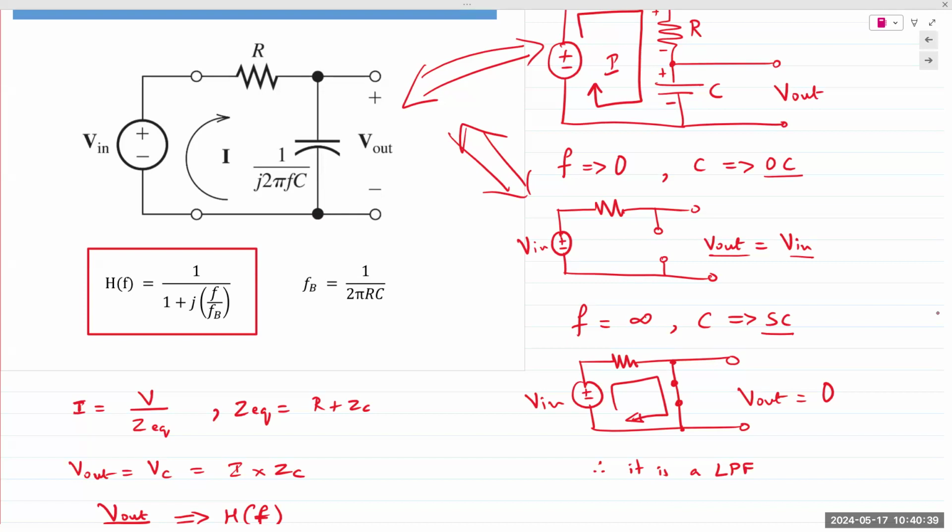So all four circuit diagrams are exactly the same circuit. There is no difference. It's only the behavior of the circuit that changes because capacitor impedance changes with respect to frequency. We are simply modeling the circuit at low and at high frequencies. Does that answer your question? Sort of.